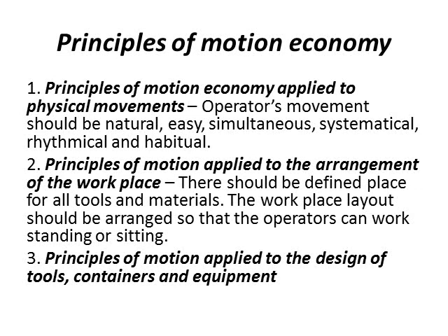Similarly, the principle of motion economy can also be applied to the arrangement of the workplace. There should be a definite place for all tools and materials. If there is a definite place for all tools and materials, we do not spend much time searching for a material or a tool. So by proper arrangement in the workplace, we can apply the principle of motion economy. Third is the principle of motion economy applied to the design of tools, containers and equipment.